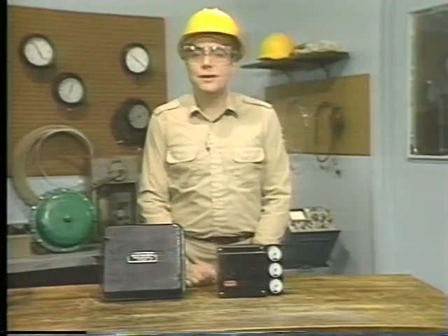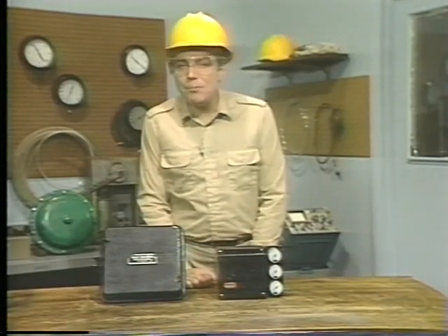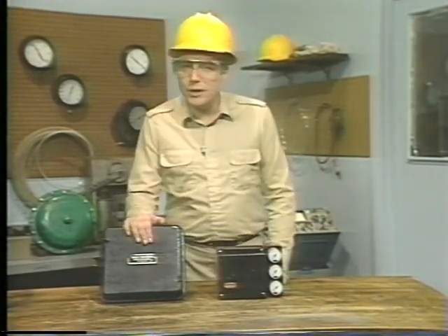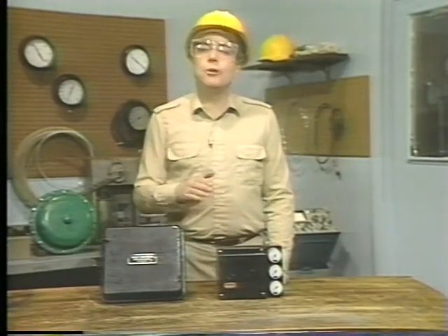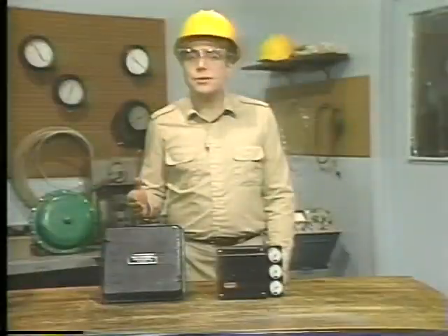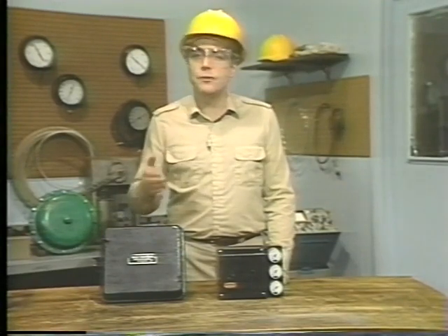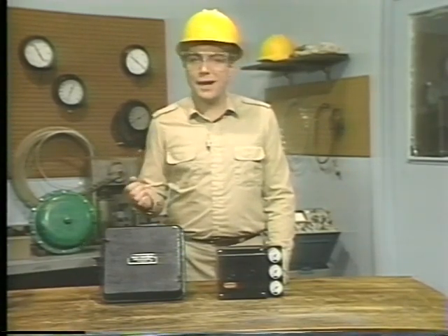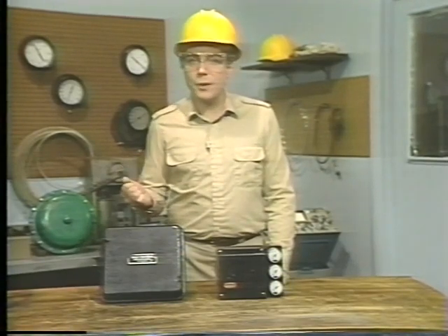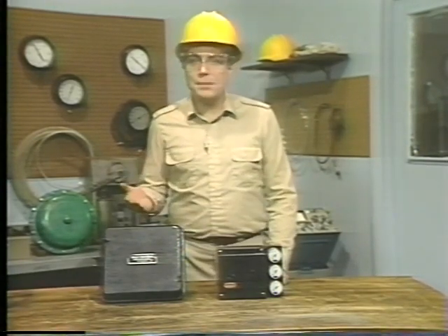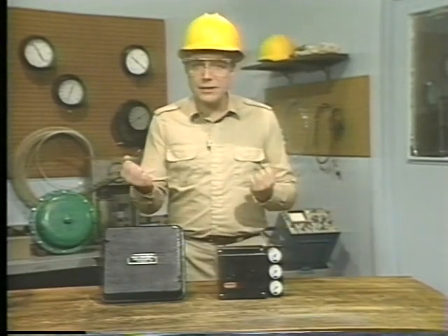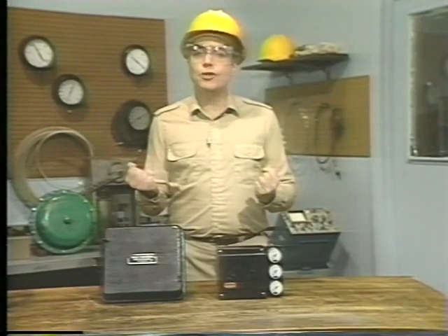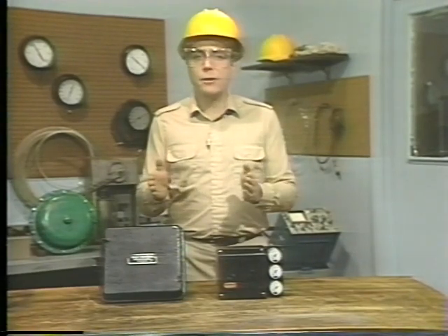The way the positioner does this is by balancing an input with an output. For example, the force balance positioner that we just looked at balanced an input force caused by the expansion of a bellows in relation to a signal from a controller with an output force caused by a spring in relation to the position of an actuator. In other words, a force balance positioner works by balancing two forces, and balance is only achieved when the actuator has moved the required amount.